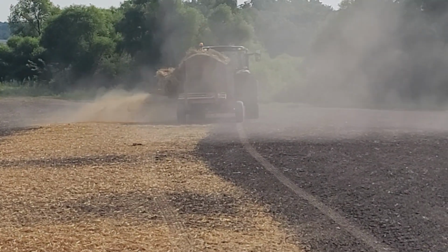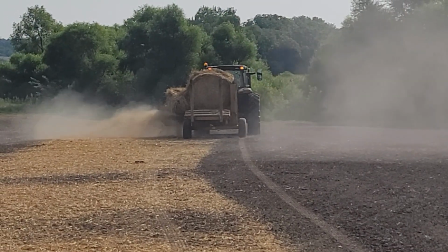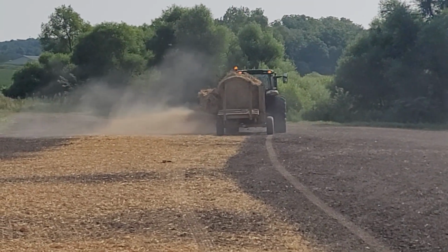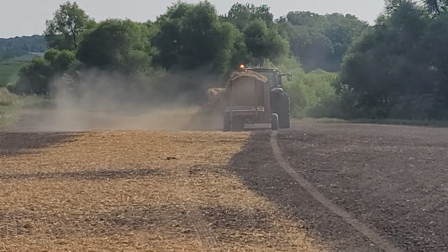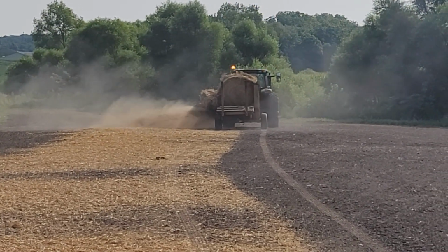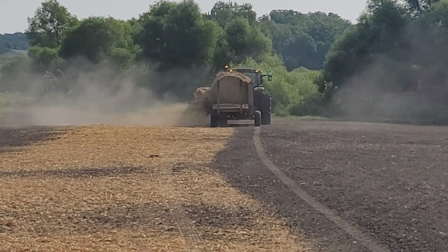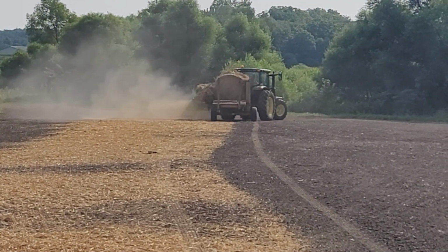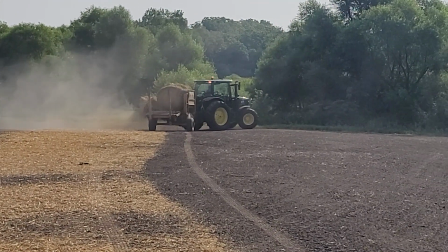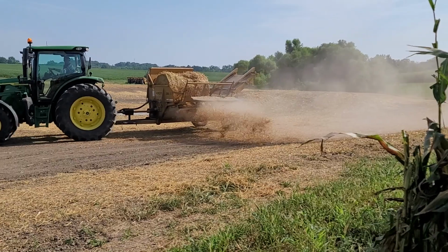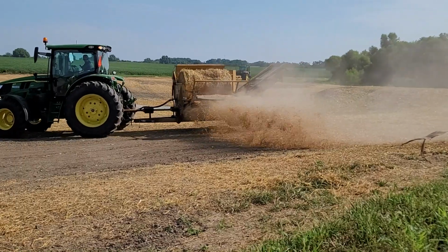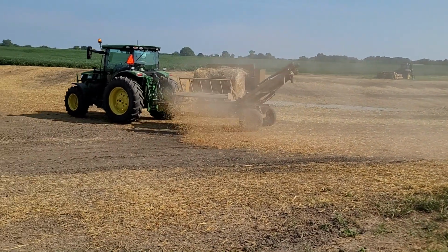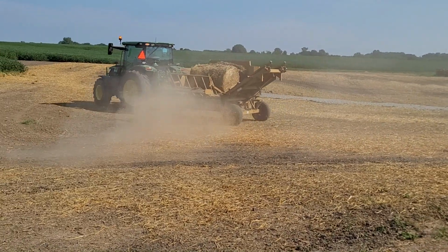The areas disturbed by the construction need to be revegetated to hold soil in place. The construction site received a lot of vehicle traffic during installation of the structure. Before the contractor could put seed, fertilizer, and straw mulch, they prepared the seedbed, eliminating compaction and clods and loosening the soil surface in order to get good seed-soil contact and ensure successful germination. For this site, they planted a commonly used conservation seed mix. Straw mulch was added to help keep the seed in place and hold moisture in the soil.